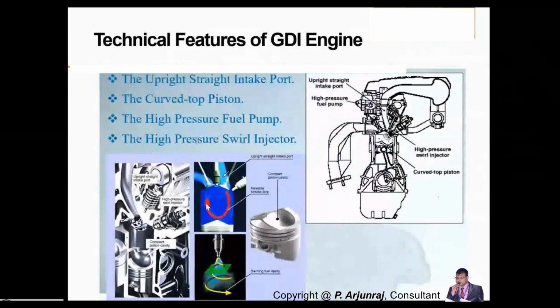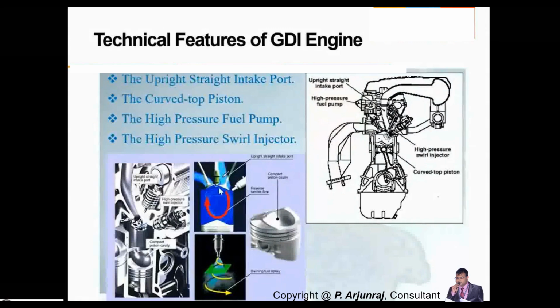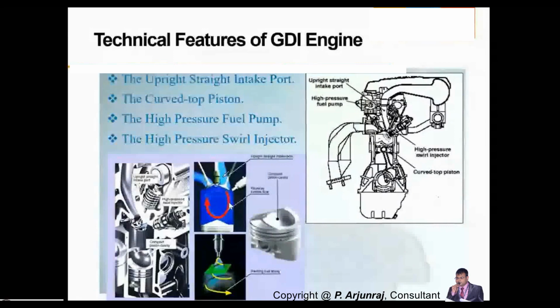If you have higher pressure, irrespective of the mode of mixture like rich or lean, even if it is a rich mixture where you have a higher amount of fuel than air, with the help of the tumble flow or a swirl flow, since you are going to create a reverse flow with high pressure or high velocity, you have less time for the reaction to take place between the air and fuel in the system.